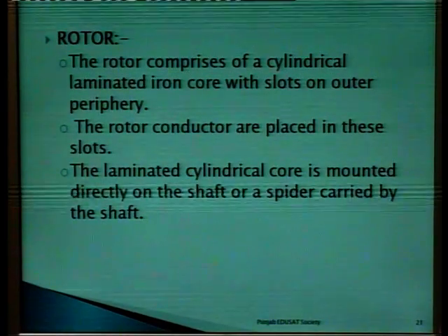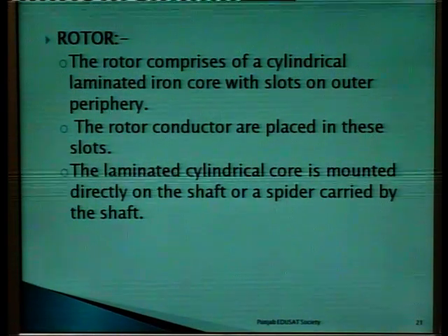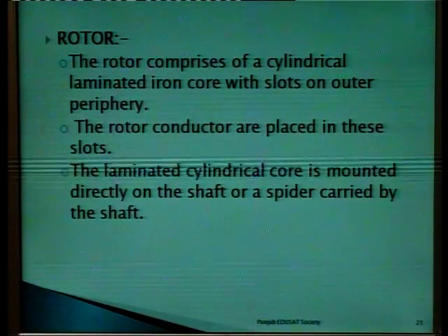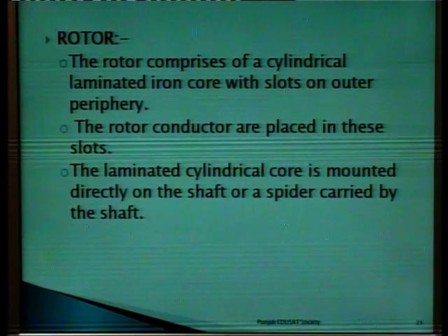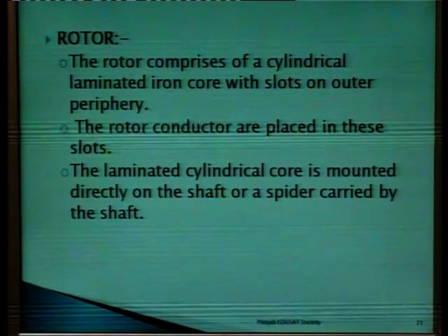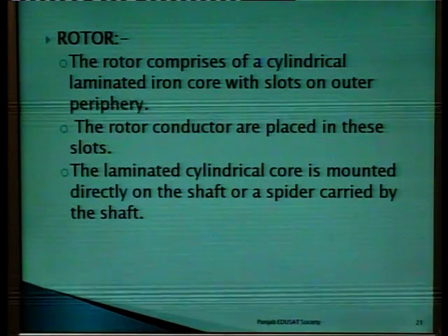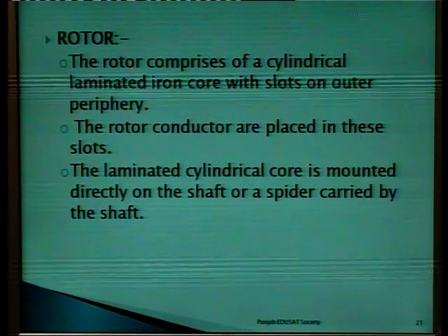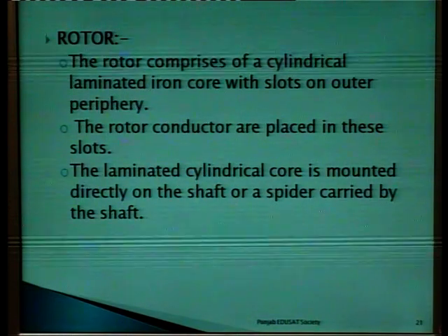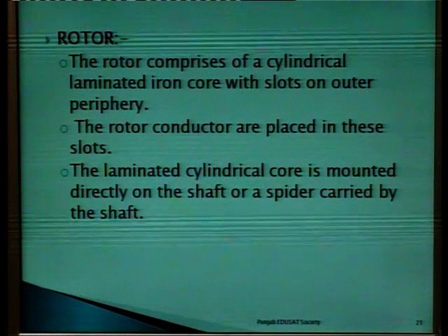Next is the rotor of the induction motor. The rotor comprises a cylindrical laminated iron core with slots on the outer periphery. The rotor conductors are placed in these slots. The laminated cylindrical core is mounted directly on the shaft or a spider carried by the shaft.